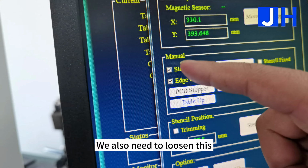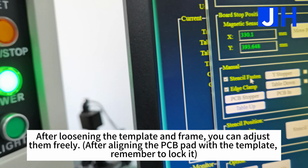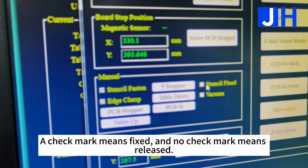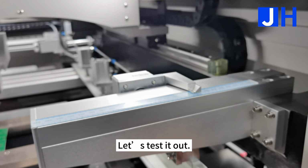We also need to loosen this. After loosening the template and frame, you can adjust them freely. After aligning the PCB pad with the template, remember to lock it. A check mark means fixed and no check mark means released. Let us test it out.